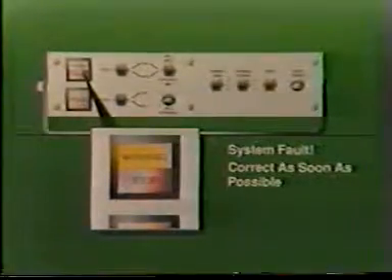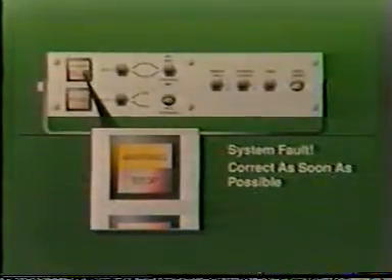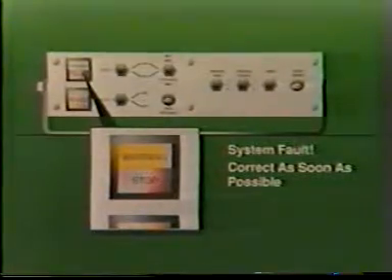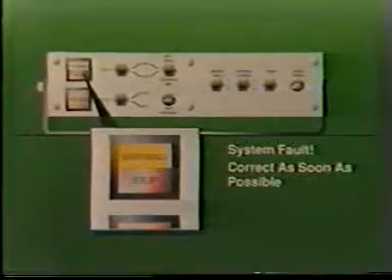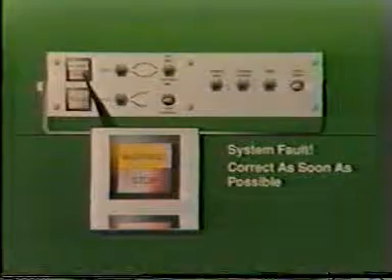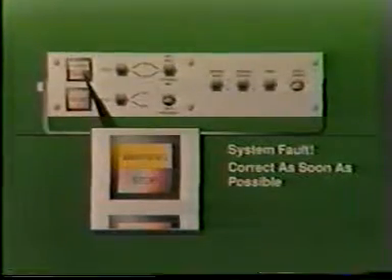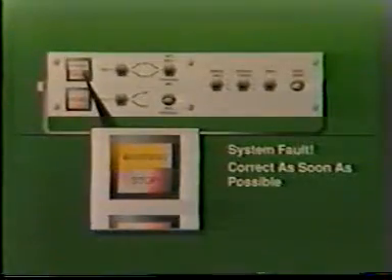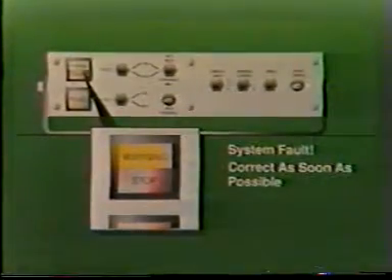The yellow warning lamp is used to warn the operator that a component or system has logged a fault. The vehicle can continue operation, but the conditions must be corrected as soon as possible. The red engine stop lamp is used to warn the operator that a major system problem has occurred. The vehicle should be shut down as soon as possible.